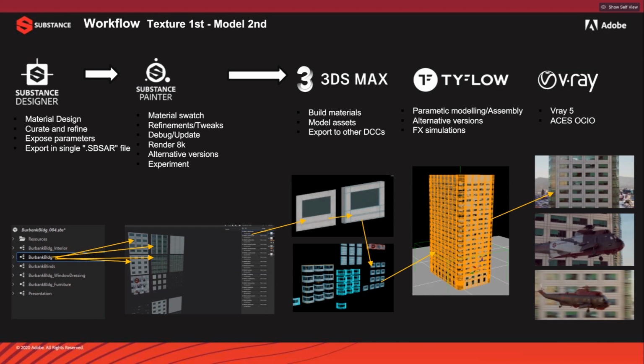There's 12 little windows, and each one gets offset. At the top level, because it's 1, 2, 3 at the top, each one will get offset by 0.333333333. And then the ones down, 1, 2, 3, 4, they're offset by 0.25. So all of those 12 little windows exist on the same UV plane. And then it goes into TyFlow, so assemble the building.